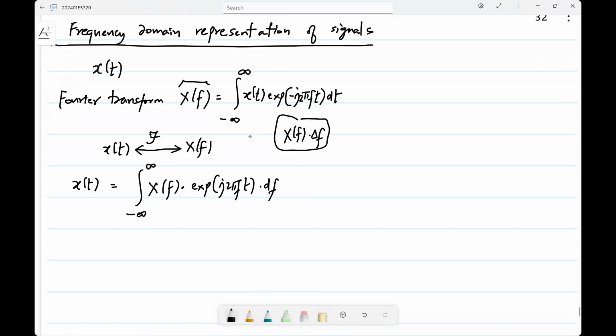Of course, we usually don't directly use these formulas to calculate; that you would have done in the first Fourier transform course. After that, you know the Fourier transform for some standard signals and you go with that. But now, can we use it for every signal? Are there some terms and conditions that limit you? It should be absolutely integrable. Basically, it should have finite energy, right?